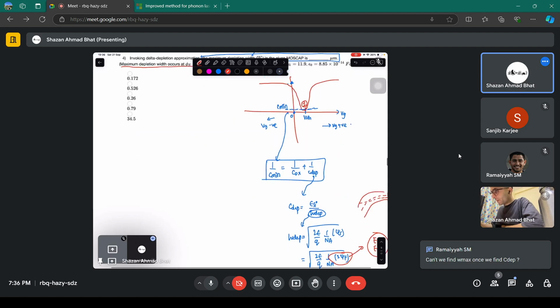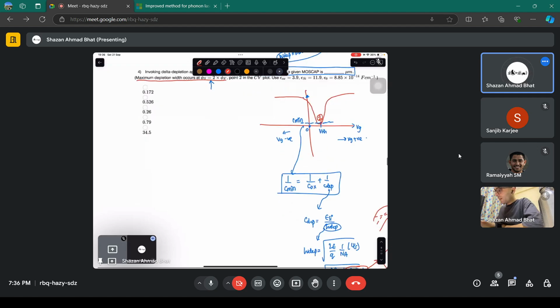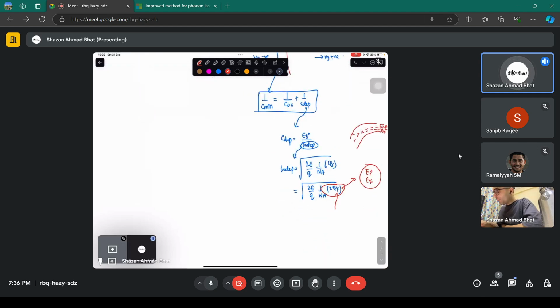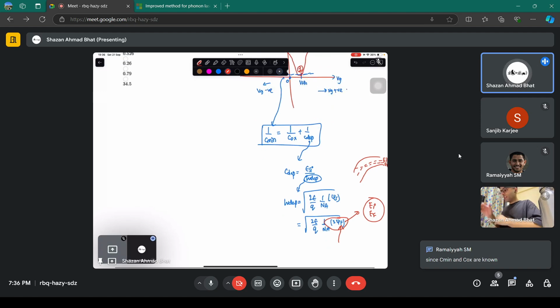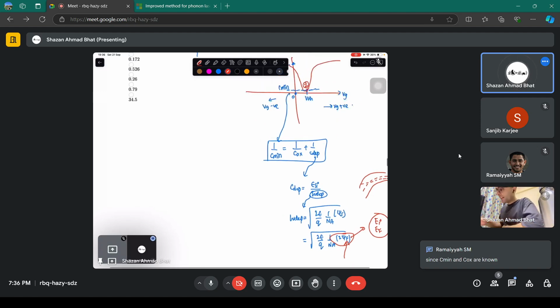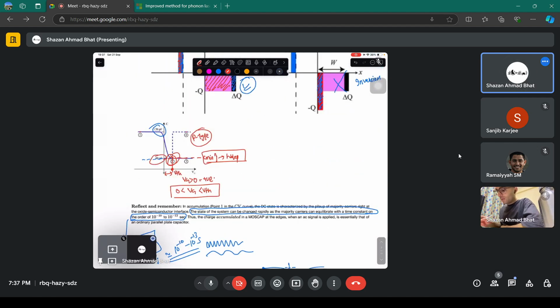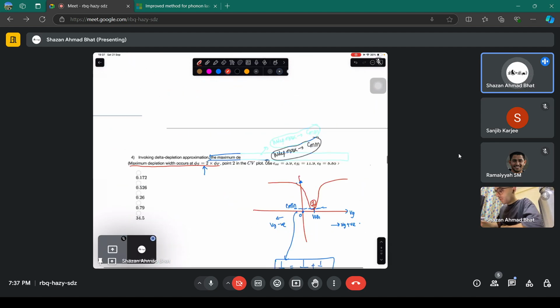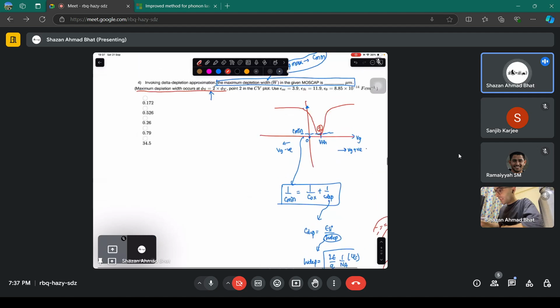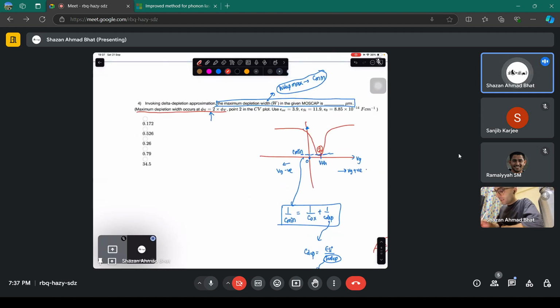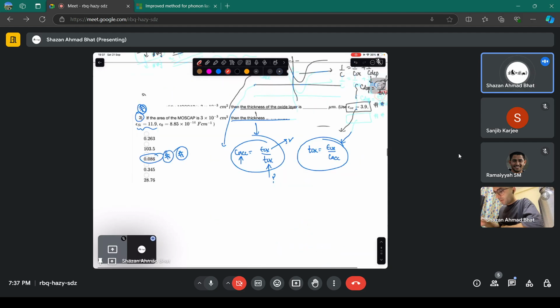Okay. So what you have to do, because you cannot know the Fermi potential from this approach I just showed, this is the general approach, but from the figure, you are given this value, 40 picofarad. Directly use it here. You can use C depletion is equivalent to epsilon silicon divided by W depletion. Is this particular value given?